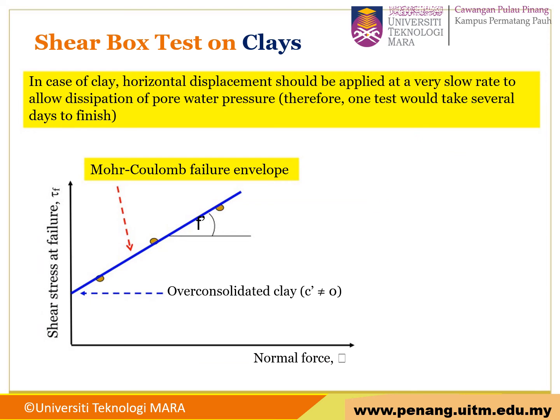Alright guys, look at this. This is a shear box test on clay. In the case of clay, horizontal displacement should be applied at a very slow rate to allow dissipation of pore water pressure. Just one test would take several days to finish.